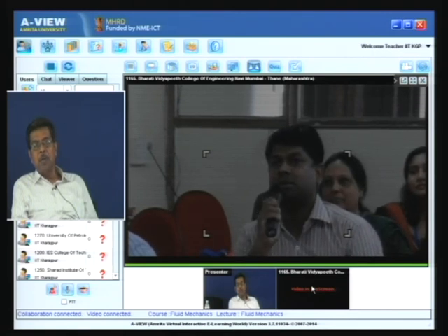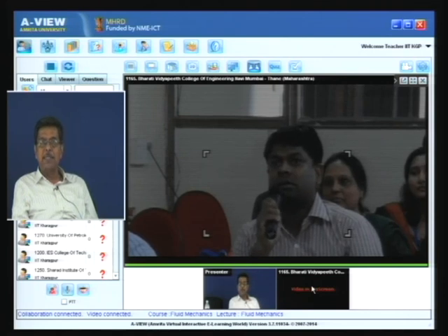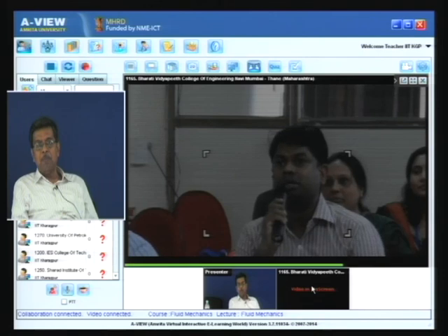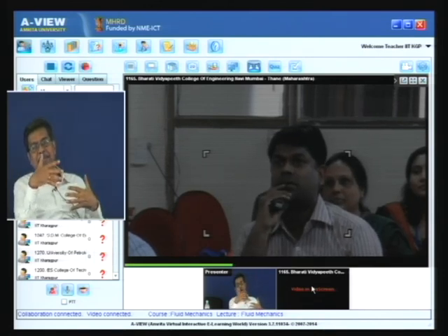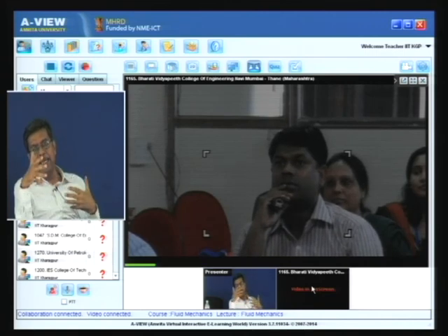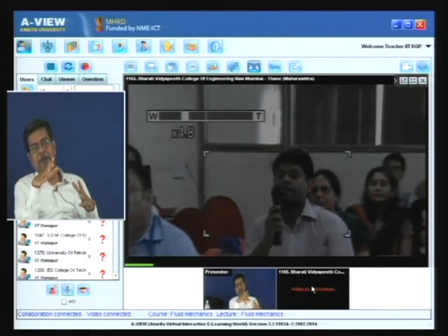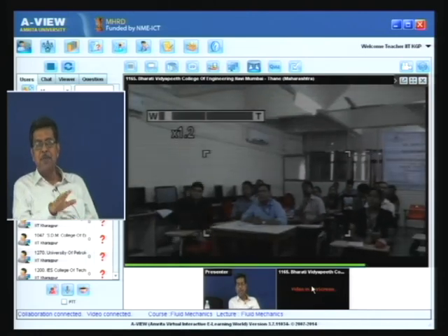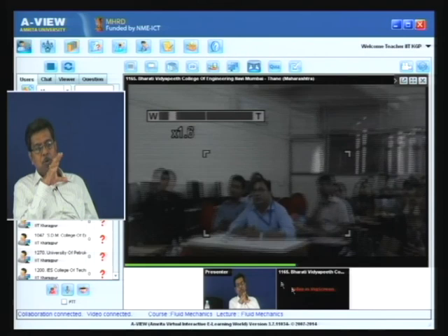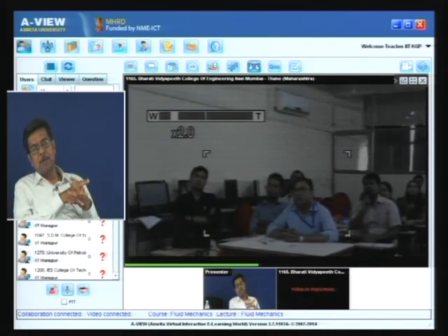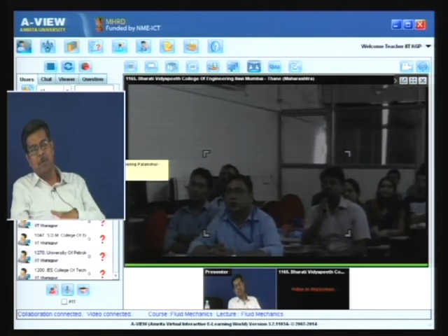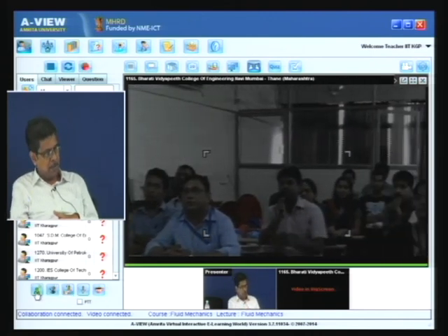System is always moving, and control volume. What are the system boundaries? System boundary may move, system boundary may expand, system boundary may collapse, doesn't matter. This is not mattering much. Okay, system is moving, but control volume is fixed with respect to the coordinate axis. But if control volume is moving, in that case, the coordinate axis is attached to the control volume.